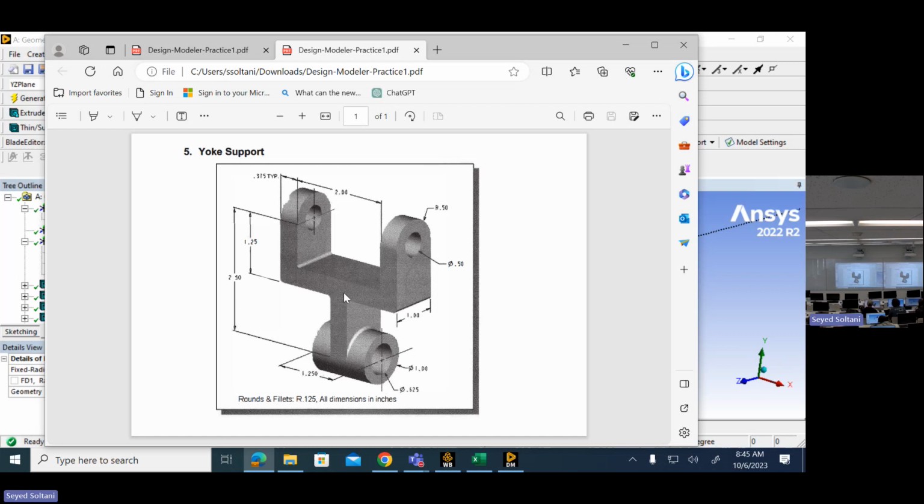If you look at it, how many axes of symmetry do we have in this case? Obviously, the one that cuts through the material over here, which is our XY axis, is an axis of symmetry. But there's one other axis of symmetry, because of the way that we constructed this. It's the one that cuts right in the middle, and that would be the YZ plane. So now I'm going to slice the part with these planes so that I will get portions of the model. Good, and I'll show you how we can leverage this into taking the analysis further.